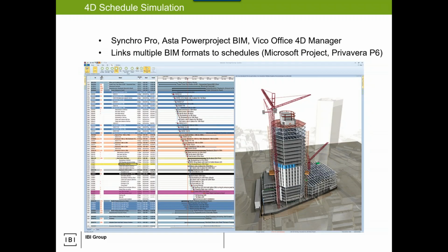Schedule simulation. So when we talk about the BIM uses in week 6, part of the critical thing for project definition and deliverables is, if you've defined that we will do schedule simulation, what are you going to do? Let's say I'm working on a DB project, design-build, for the contractor, and I know the contractor will be using Synchro, Power Project, or Vico, or something else.